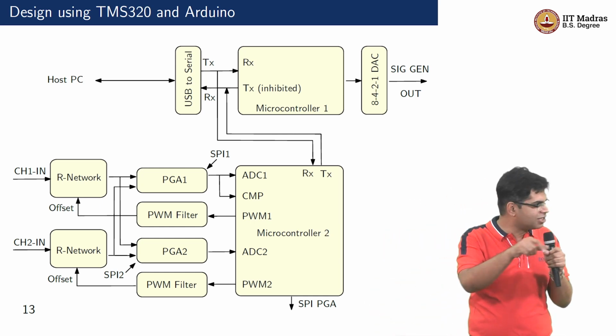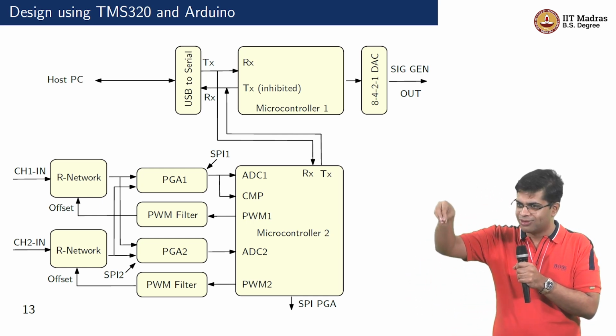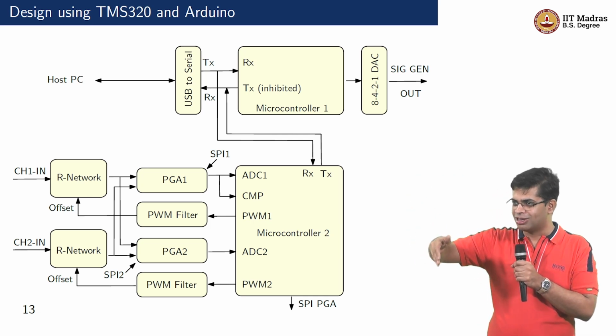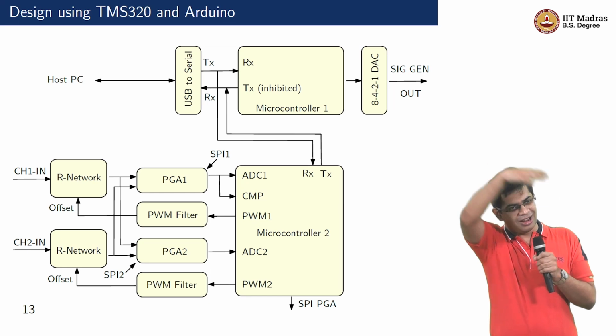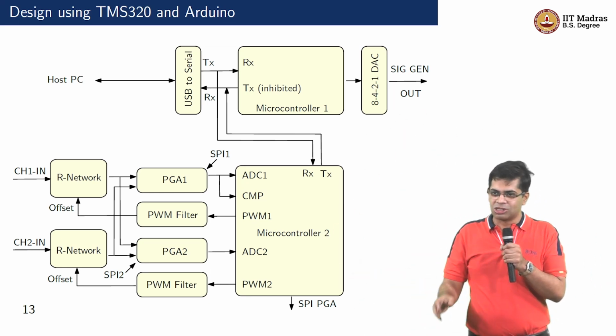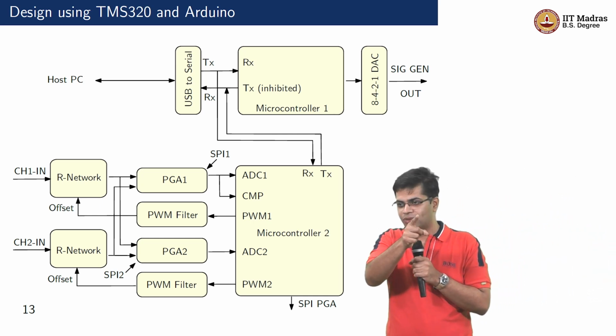And you'll see that the surface mount version of the Arduino uses one Chinese off-the-shelf USB to serial converter. It's called CH340. But in that itself, there are a whole lot of clones to keep the cost low. And those clones are all undocumented. They will work for the Arduino. But the moment we try and do what we are trying, it will not work.